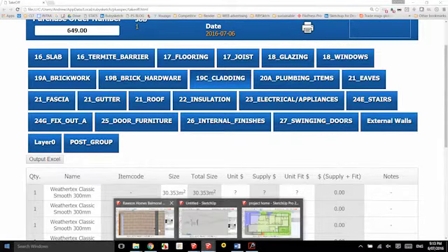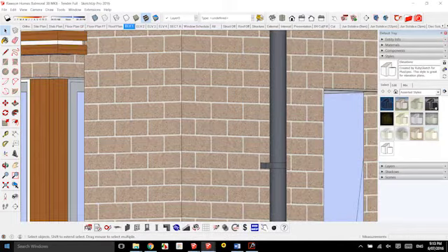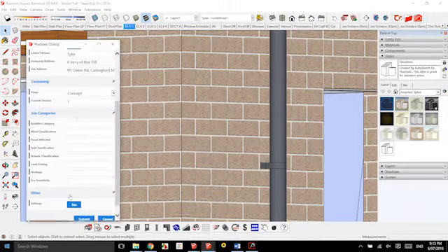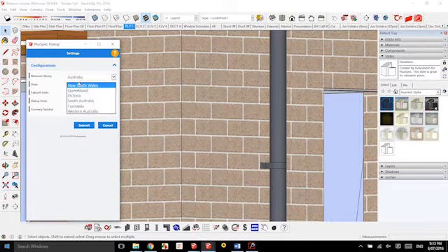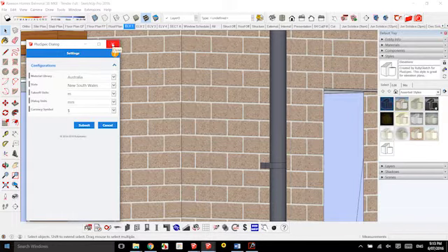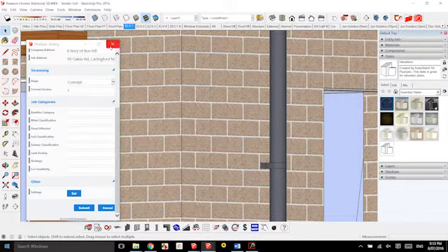So you can go inside the model, and before you start, obviously most of us are from New South Wales, so if you went to, say, a setup tool, to set up this tool, we can go to settings and we go Australia, New South Wales, Queensland, and we click sync, and it will give you every single brick that's available in your country, and it will size it for you. We never go in and tell the wall how thick it is. You'll notice that when Grant starts to draw, he's not going to tell it how wide the studs are, he's not going to tell it how wide the bricks are, because we took the information from the manufacturer.